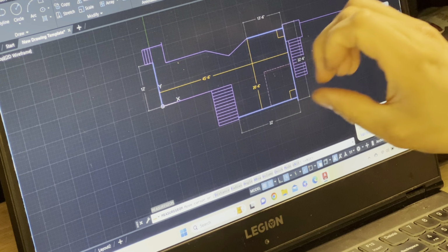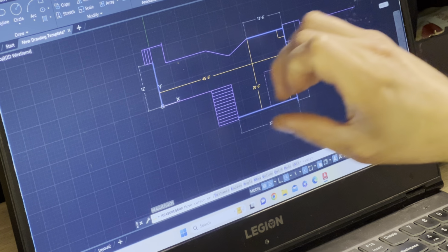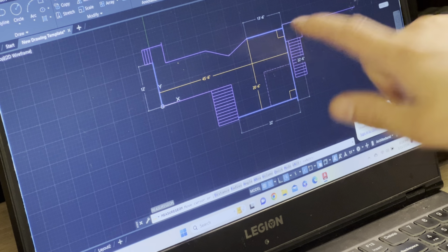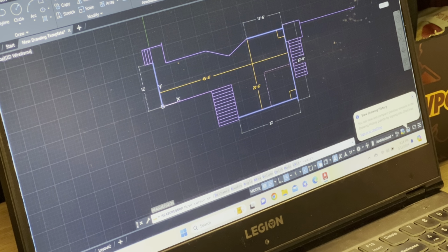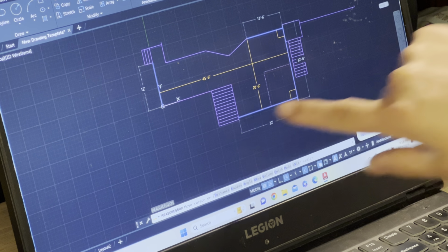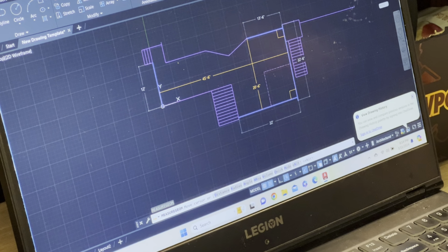So I can actually triple up the header out here, and that'll be 4.5 inches plus the ledger, right? That's going to give me 1.5 inches. So out of a 20 footer, and maybe if you get lucky, because sometimes our lumber comes at like 20 foot 1 inch, and they're actually pretty square. So every once in a while, you can max that out and just barely skim the edges out here after you snap a line, right?